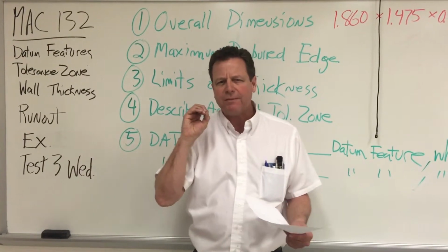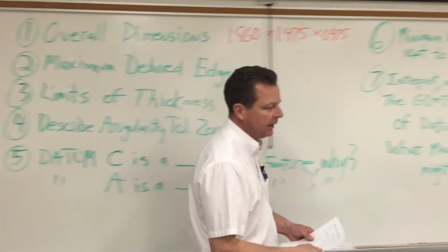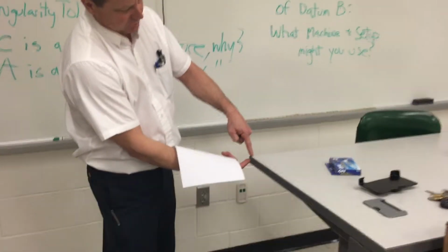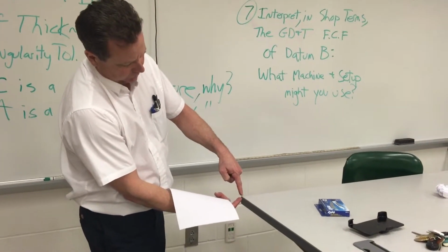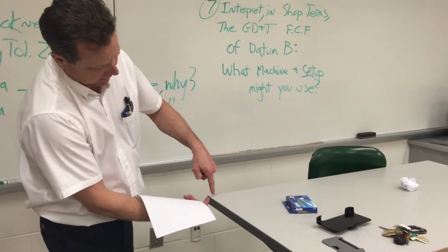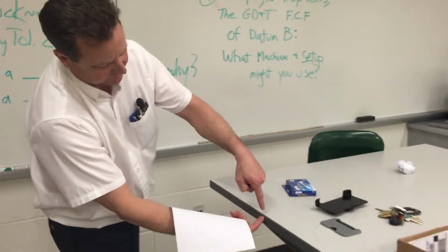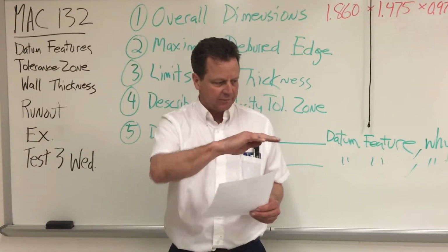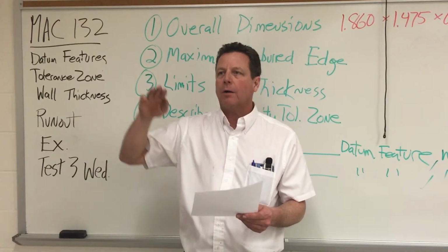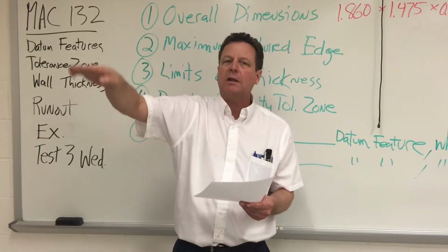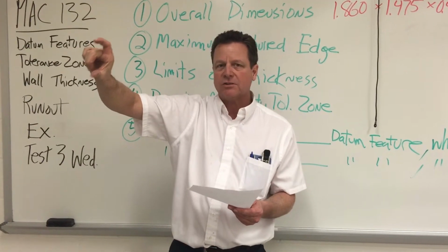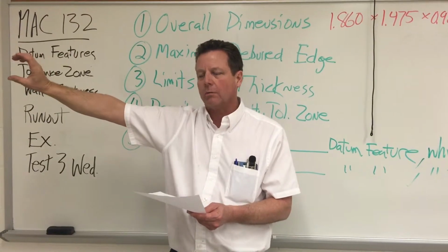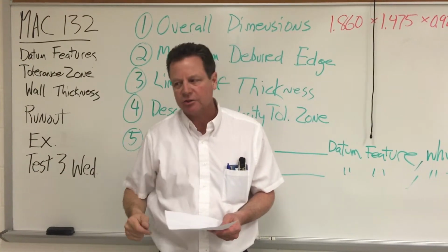What is the shape of the tolerance zone? We had like this edge right here. If this were straightness, the tolerance zone would be two parallel lines, let's say 5 thousandths apart, along the line of the thing. And our part, to be good, would have to lie in that zone that is drawn or created around that straight line edge.